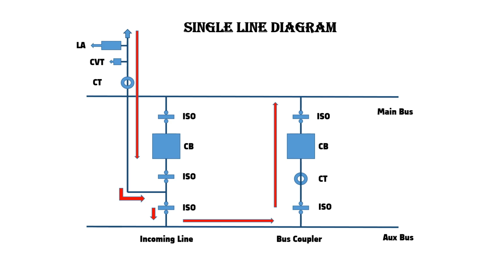But to simplify it, we can use GOOSE communication, which does not need any wiring between these two panels, and only a LAN cable is required, and the process is much faster than the conventional way.